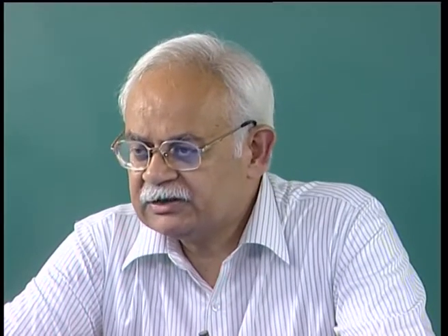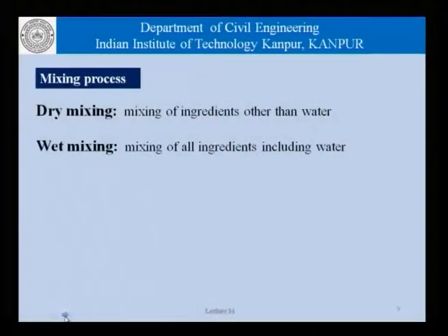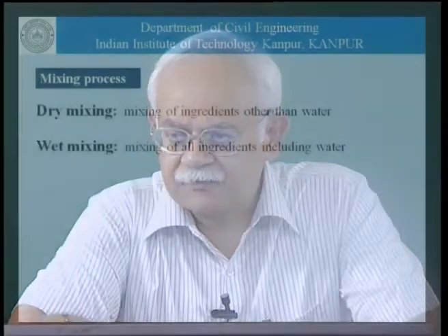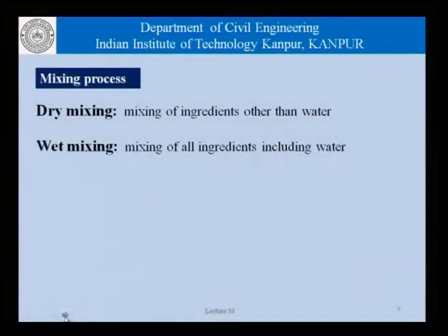Now, the minimum mixing time is therefore measured from the time when the ingredients start getting loaded onto the mixer until, finally, the concrete is poured out of the mixer. It is not necessarily the case that all that mixing time is required, and therefore, one might like to study the actual concrete being used at different mixing times if the cycle time involved is at a premium.